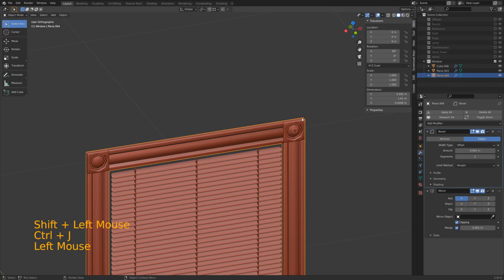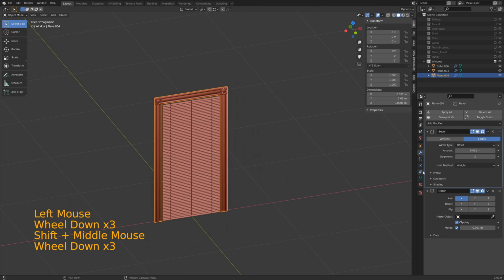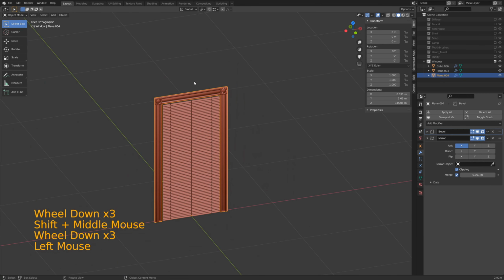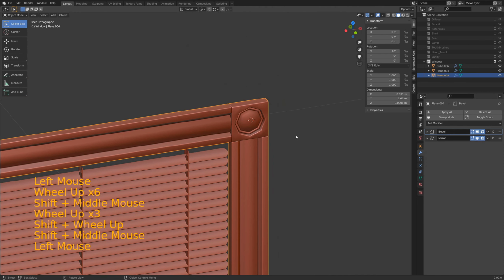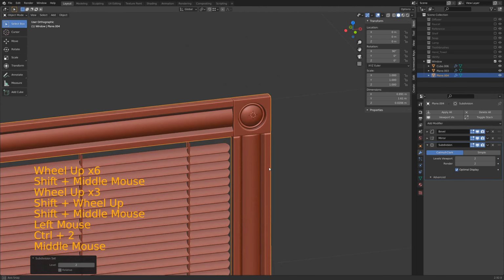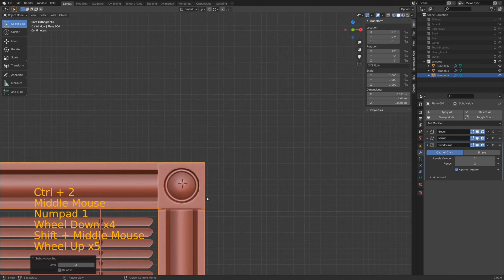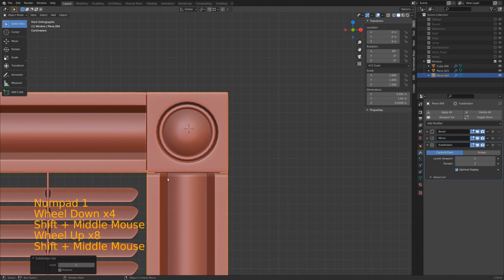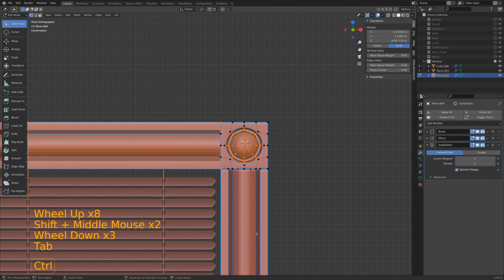We'll turn our beveling back on, and we did not apply a subdivision, so let's do that now. There we go. And we've got some wonky edges going on here. Some of the shading's not quite right. That is because we just don't have enough geometry.